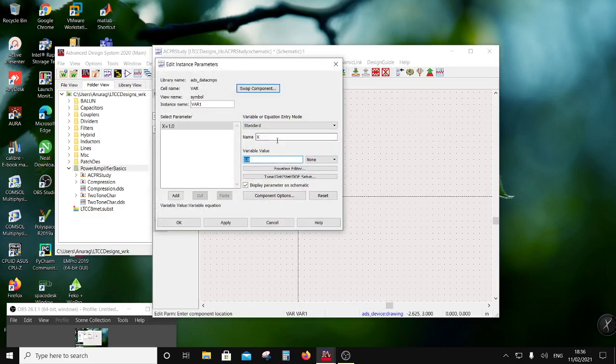First of all I need to know the bit rate, and let's say that this bit rate is 76 megabits per second. Then we are going to do a QPSK. DQPSK is a form of QPSK, so basically you are taking two bits and forming a symbol. So the symbol rate is going to be half of the bit rate, bit rate by 2, right?